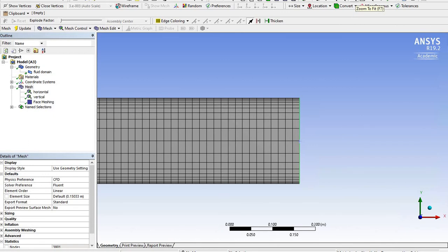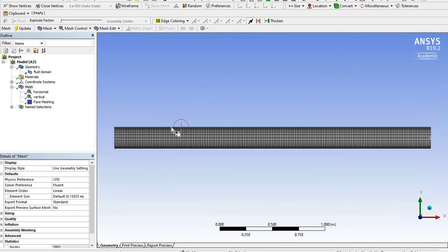Look, I didn't specify the top and bottom or the middle section. You can do that, but if you don't, by default, whichever is not defined, ANSYS takes the edges as wall and the middle part as an internal region. So this is the same thing I was going to define, so I just skip this one. By default, it is the same thing. So I need to apply boundary conditions at the inlet and the outlet. That's why I did inlet and outlet. Okay, so we are done.